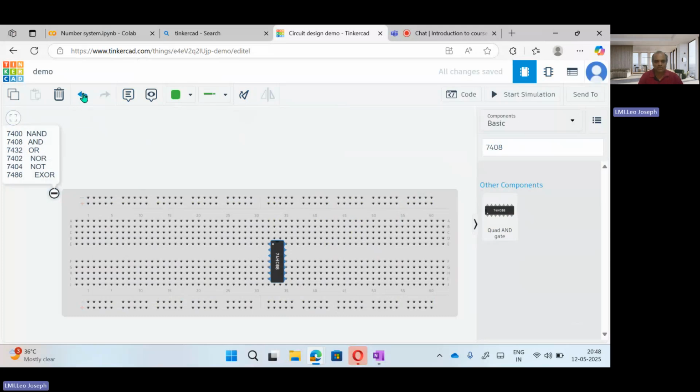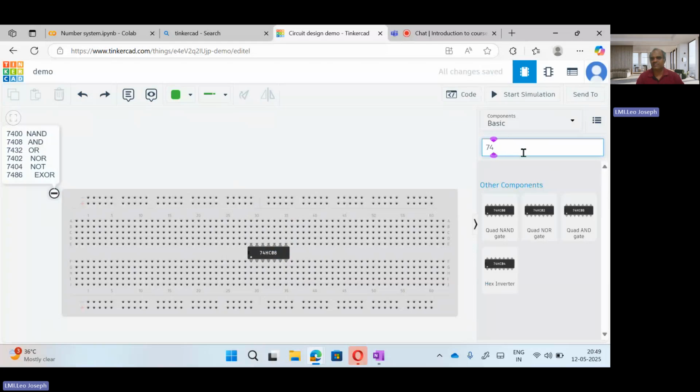So in order to avoid that, I am just fixing the IC like this, so that the center pins, vertical sections only are connected, horizontal lines are not connected. So this pin and this pin will never contact each other. This is separate and this is separate, and all pins are looking fine. No short circuits will occur. This is how we have to fix the IC.